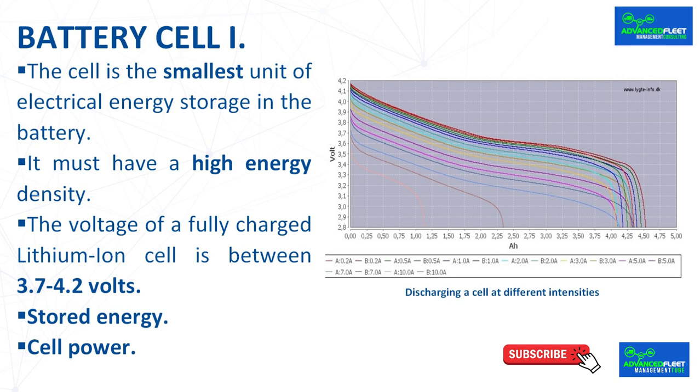In lithium batteries, the state of charge of the battery is proportional to the voltage they give in an almost linear way between their maximum and minimum. The battery voltage starts at 4.2 volts, which is the maximum, and begins to drop to 3.7 volts for most of the battery's life. The minimum voltage for lithium batteries is 3.4 volts. At this voltage, the battery is dead.